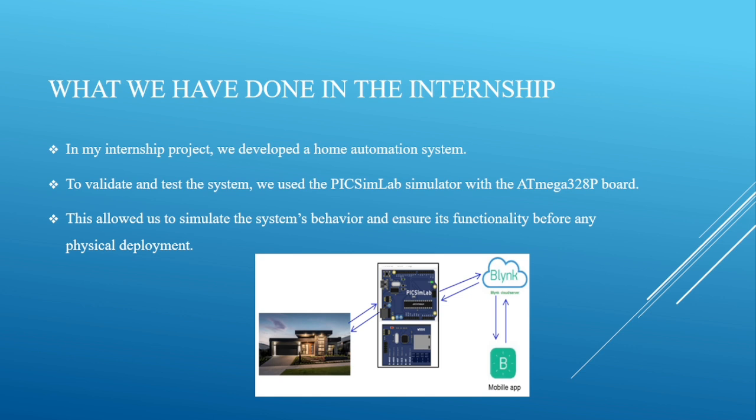PicSimLab allowed us to create a virtual environment to develop and test our embedded system without physical hardware. I wrote and tested the control code using the Arduino IDE, which was compatible with the simulated Atmega 328P microcontroller.